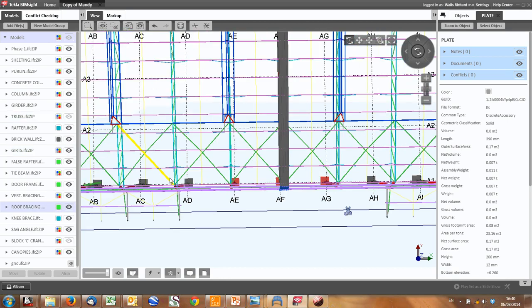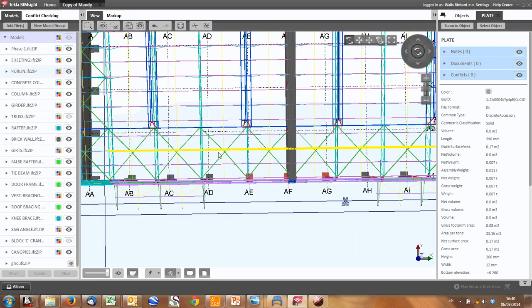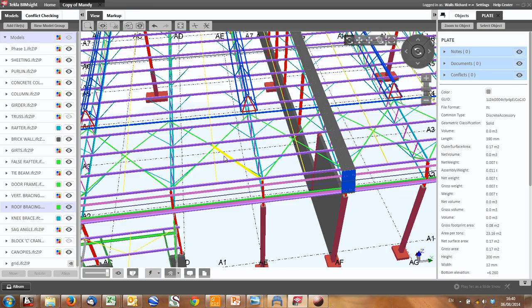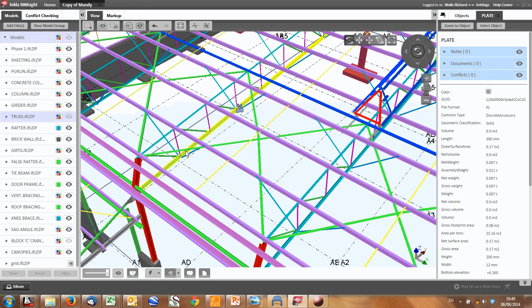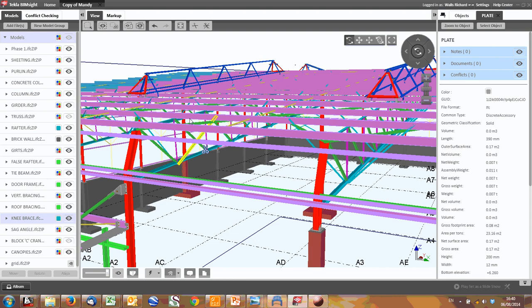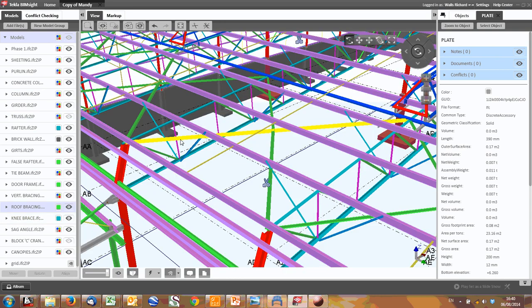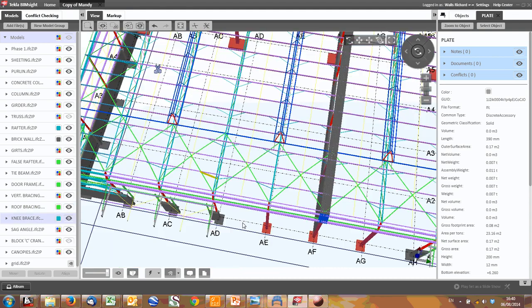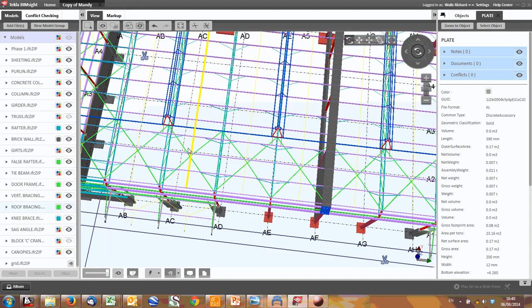So the load comes down and then puts these members into tension. Now, if you look at those, these are very long, thin members. So obviously they can't take compression. You can just imagine on the side, if you pushed on these things, they just sag out of the way. But being steel, they don't have to be very thick to provide immense tensile stiffness. So these are tension-only members.